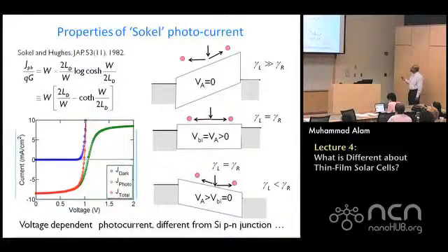What happens here is that at low voltages, this partitioning occurs. So most of the current is going the right way, the way you want it to be. When the voltage is VBI, the built-in voltage, they partition equally, the current is zero, right? So this point is where current is zero. And if you flip it to the other side, then of course the currents are going to go the wrong way. Instead of electrons flowing this way, now the electrons are going to flow to the right side. And so the current is going to flip. That's it. So voltage independence doesn't really hold in this case.